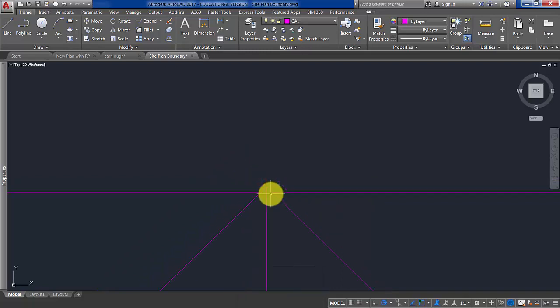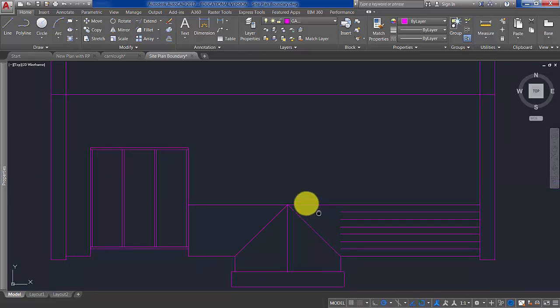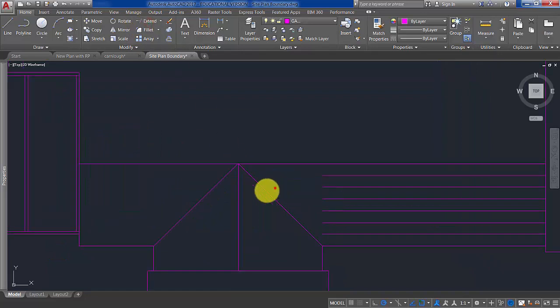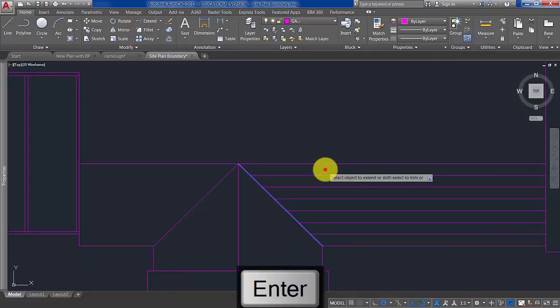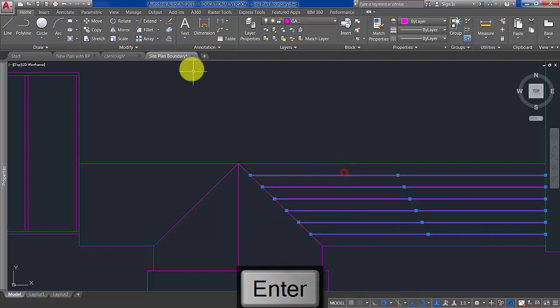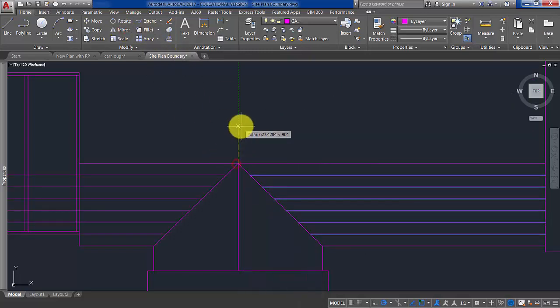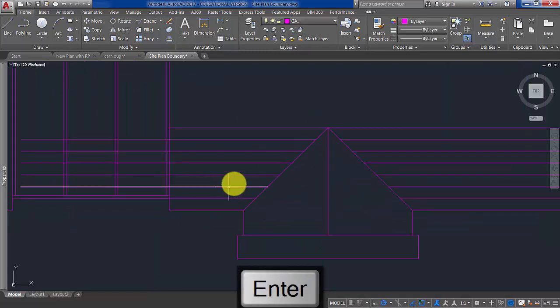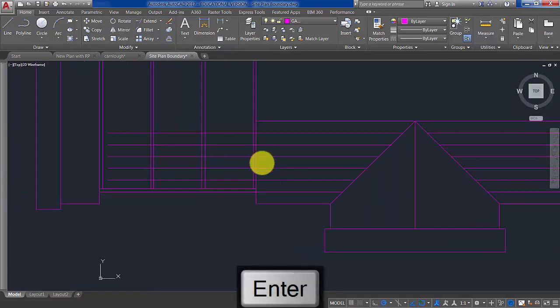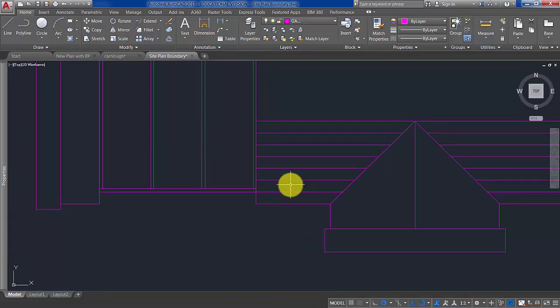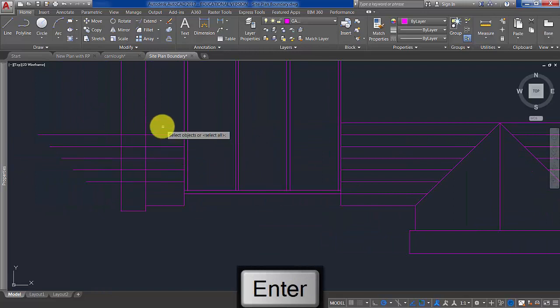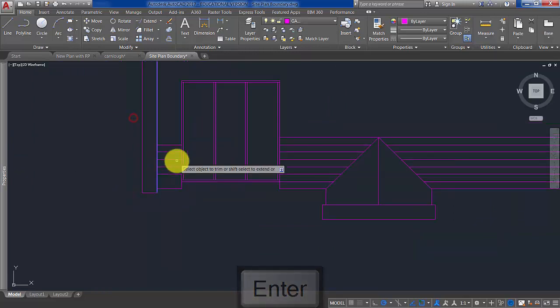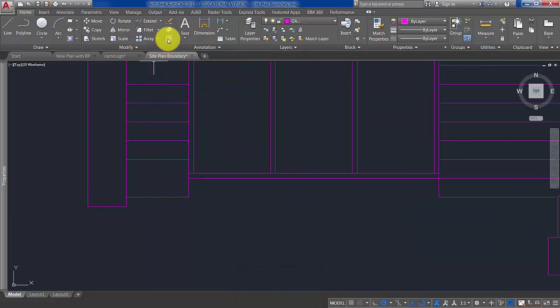You're never really going to see that because it's so small, but just to be 100% accurate, because at a later point you may move something, and then we can take that and just mirror it around the center point there, and then trim off on the other side here, like so. And then again, just for ease, we can mirror around the center point of that and trim out on the other side. We missed one.